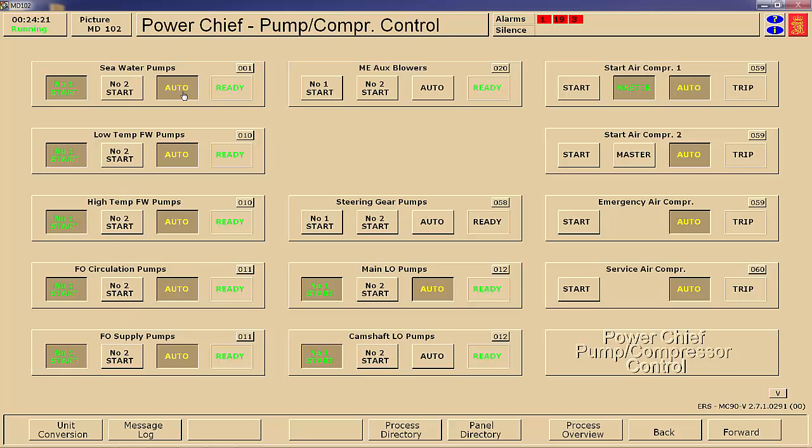Now, what we're doing is a COI, Certificate of Inspection. Every year you test the automation systems. And one of the tests that is typically done is testing to see if the standby status works. And you're going to be doing that on just 3 of the pumps. With the Coast Guard, I would be testing over all of these. But to keep this scenario in a reasonable time and to get the point across, you're only doing the saltwater, low temp, and high temperature pumps.